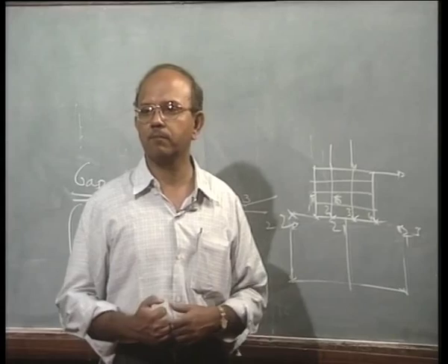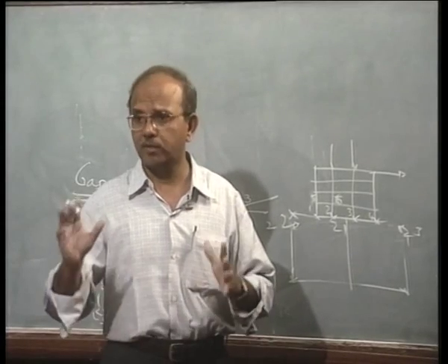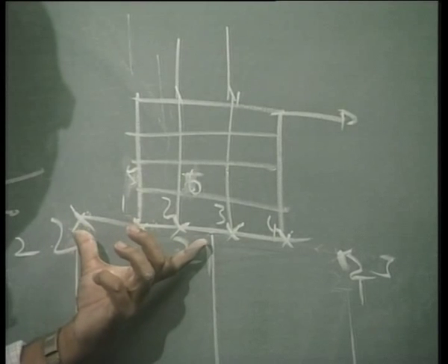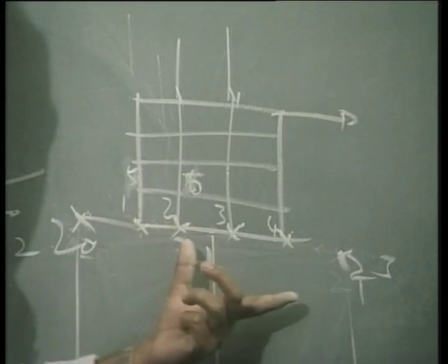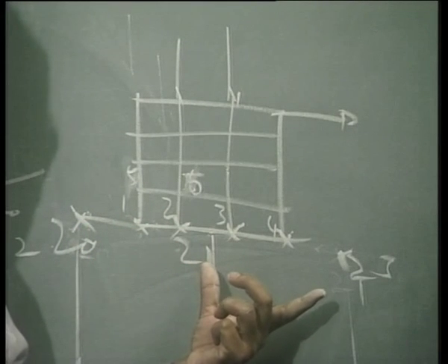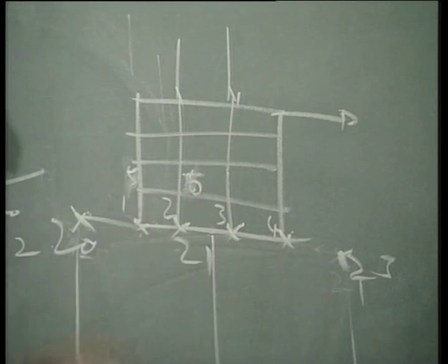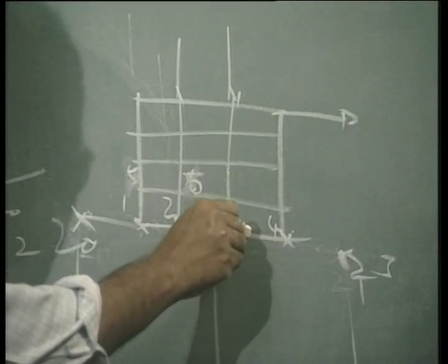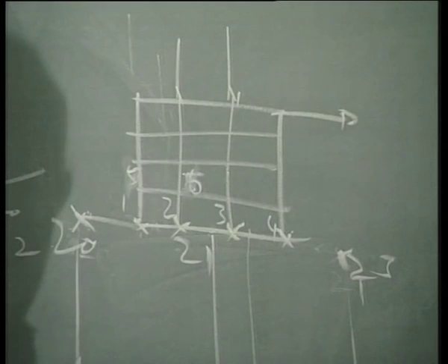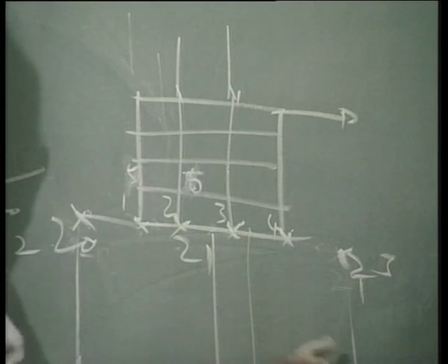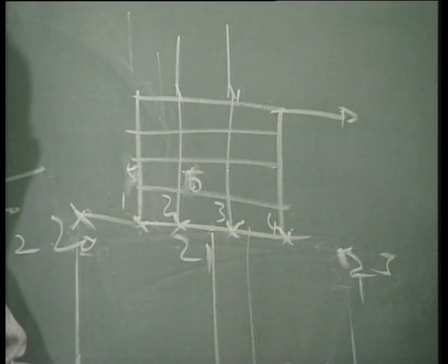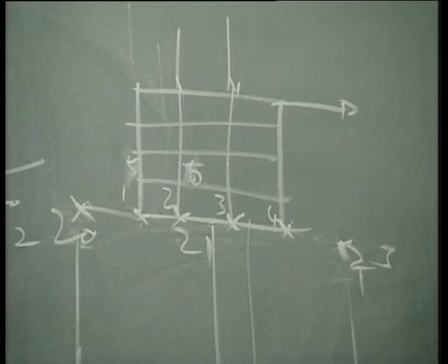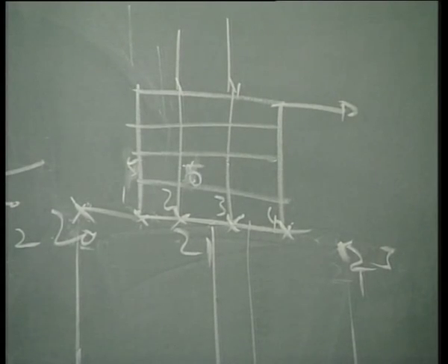In other words, if I just give 20-21 for the node 2 and forget about 21-23, and it starts moving, when it goes into this segment it will go down straight away, because you would not have given 21-23 as a master segment. These are niceties which you have to look at in the software you are using.